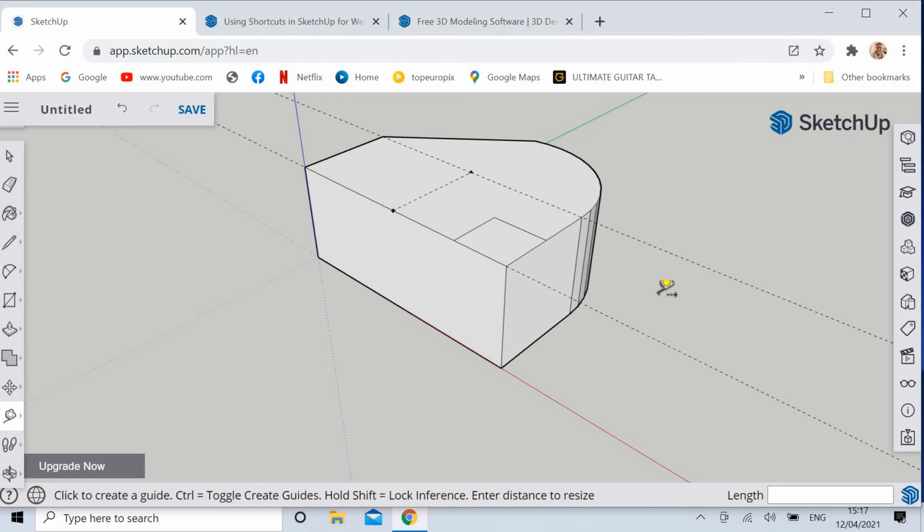I want to show you a little trick. I'm going to call back the push-pull or extrude tool. I'm going to click on here and watch this. Click once, we come down and say it's making a step, but I want to cut that away in this case. So look, I'm going to click 20 and hit enter. We know it was 20 high. Watch. That's how you cut shapes away.